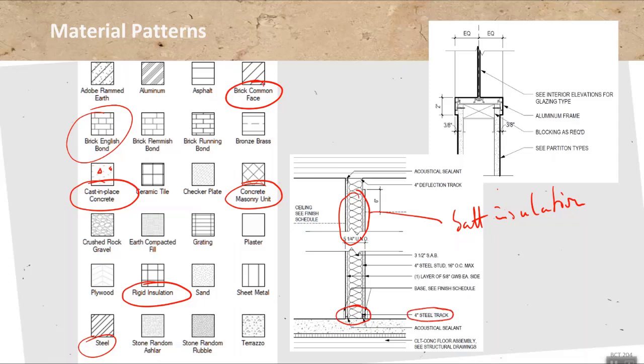If you have a light wood or a dimensional wood element somewhere in there, for example a 2x4 or anything larger than that, then it's represented, as you can see up here, as actual size and then blocked out with this cross. Glulam is represented differently with the actual layers, but any kind of dimensional wood is shown like that. In this particular case, it's still a steel stud wall, so we do have our steel channel right there, and then the wood is basically used as a nailer for the window attachment.